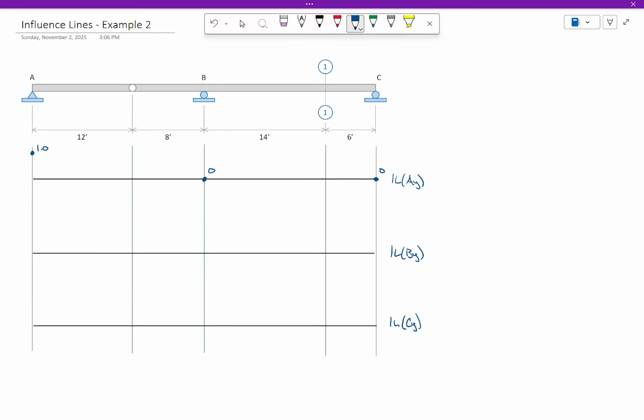How many individual beam segments are present in this beam? Is this one single solid beam from span to span, or from end to end? No, there's a hinge here, right? So again, you got to think about this like it's almost like a kinematic machine. Like the hinges, there's no deforming. It's just linearly displacing like that.